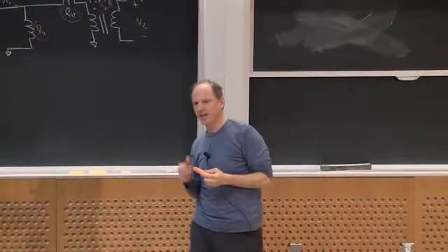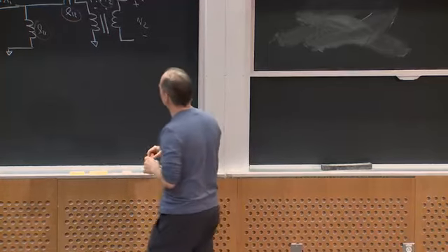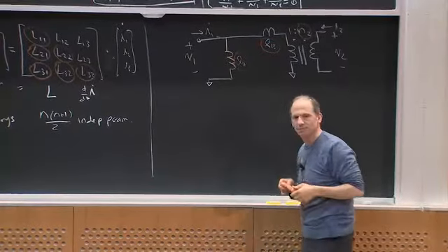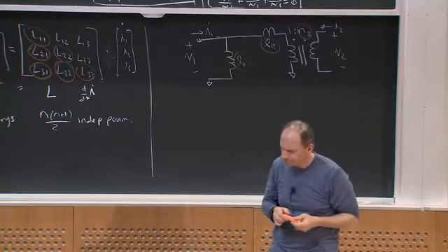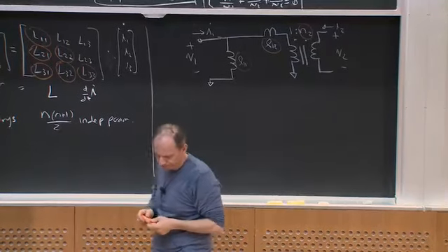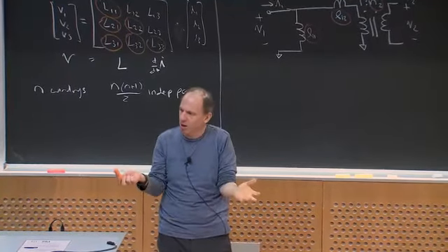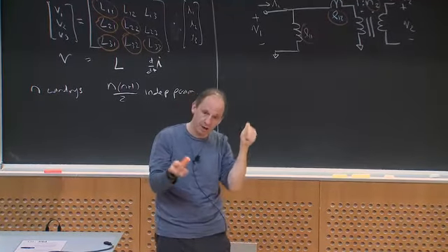So that's sometimes called the cantilever model. That's so named because you have this sort of L of inductances. Okay? That's fine. I've got 3 total parameters. I can model any 2-winding transformer that way. They're not going to be physical parameters.